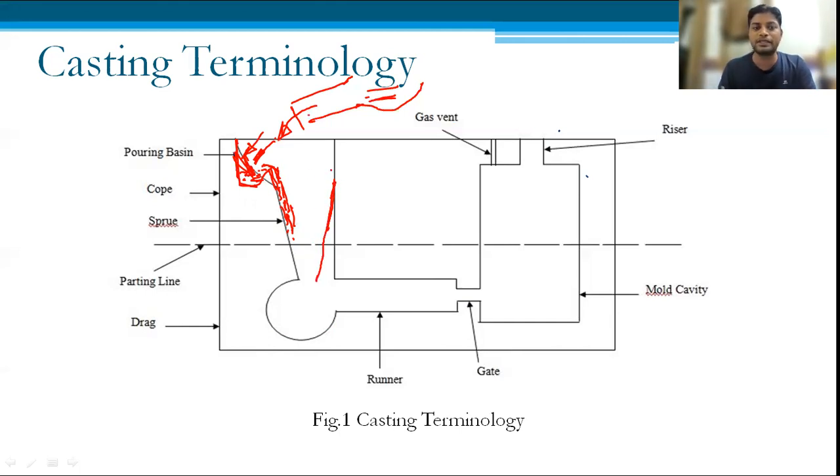So why are we using this taper? You can see that the liquid material coming along the boundary of the sprue has a very small cross-sectional area. When the liquid material reaches the exit of the sprue, we want it to be completely filled. If it is completely filled, there will be no entrapment of gases. The air coming in will move out due to the pressure difference. We do not want air entrapment here, so to avoid this defect we use this taper in section, the sprue.